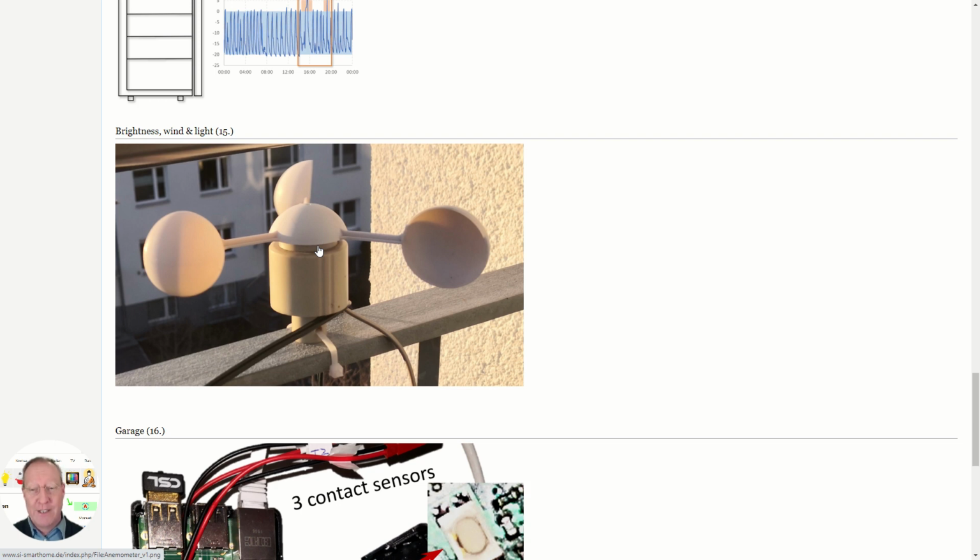So I made an analysis, I measured the cycle time, and actually an old simple Raspberry Pi, I think it's a B version, could detect the sensor signal of the two sensors in here 30,000 times per second. I have been thinking a little bit and I thought, well, this wheel will never turn 15,000 times per second. That's impossible. So the Raspberry Pi is capable of the highest wind speed which it will be exposed to over a long period of time.